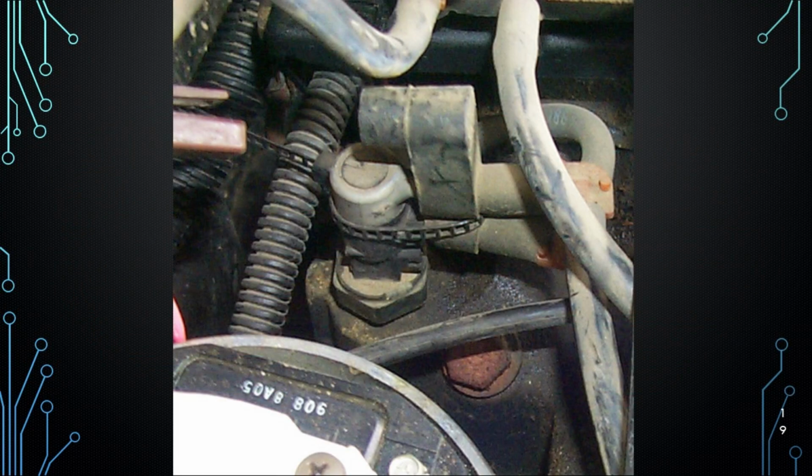So we'll go ahead and talk about this last item. This last item here that we're going to look at is a thermal switch. These were used back in that era, from, I think, the late 50s all the way up somewhere into the 90s. I don't remember seeing anything after that. They would thread it into the intake manifold, looking at the coolant temperature. So when the engine would reach a specific temperature, it would allow vacuum to flow or shut it off. There was a wax pellet inside of the thermal vacuum switch, and as it expanded from the heat, it would either open or close a passage.